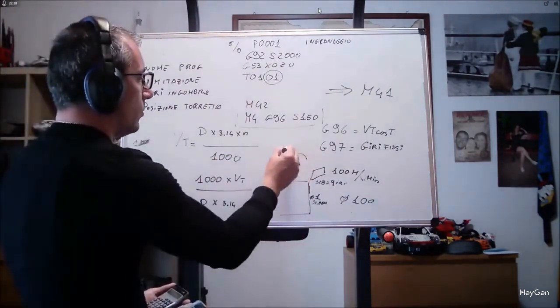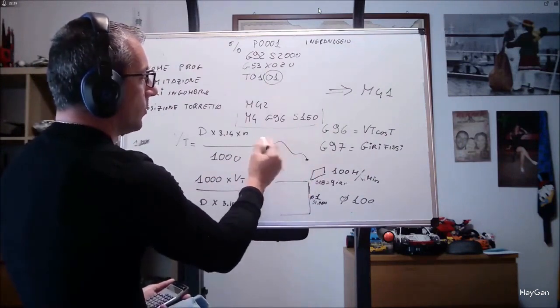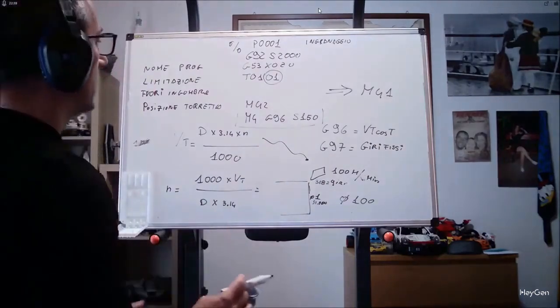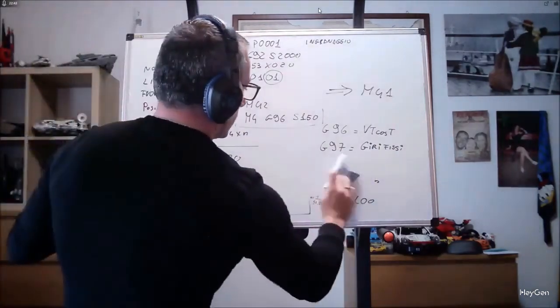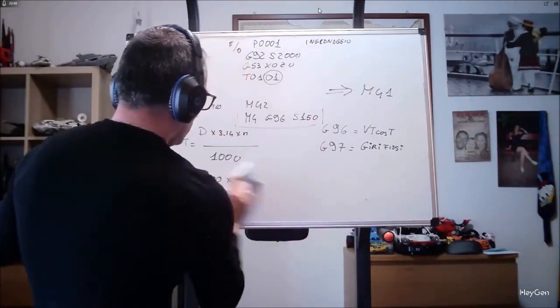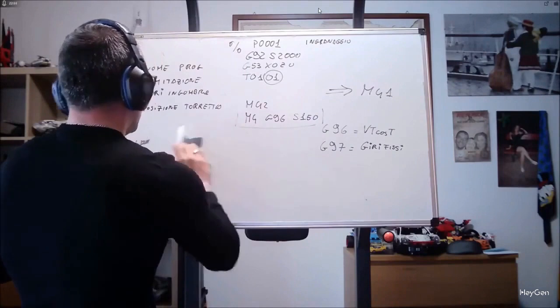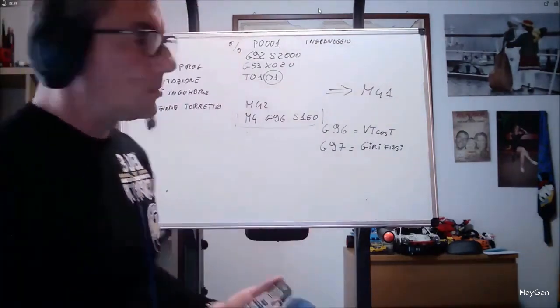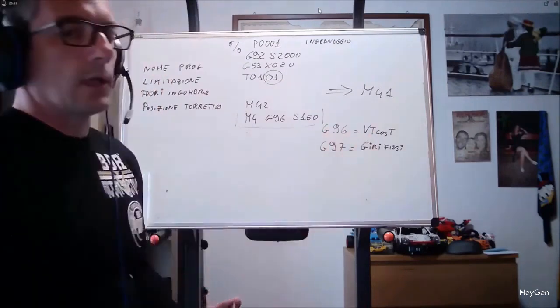So even when we create a profile, if we start here at 1000 revolutions, one minute later we will be at 500, 600, 700 RPM, like this. I like such a beautiful blackboard in chaos. Just as we can adjust the way the spindle rotates, in fixed RPM or constant cutting speed, we can adjust it.